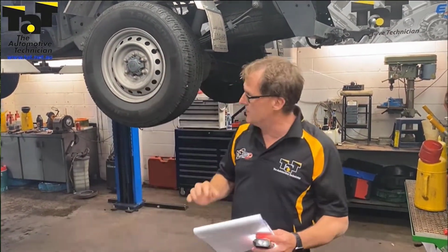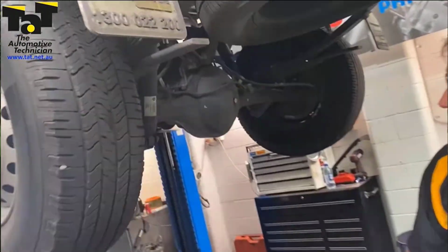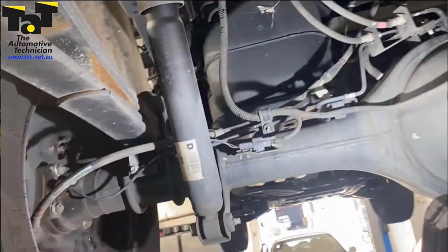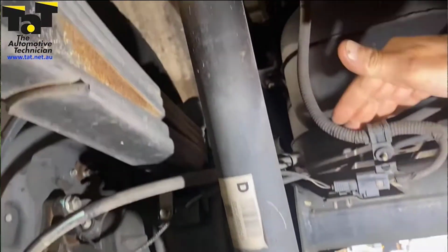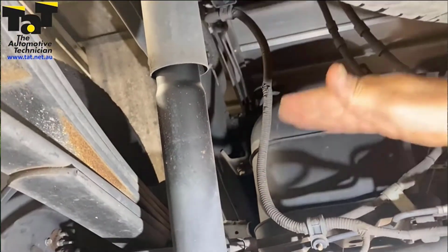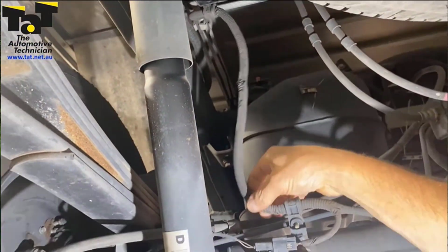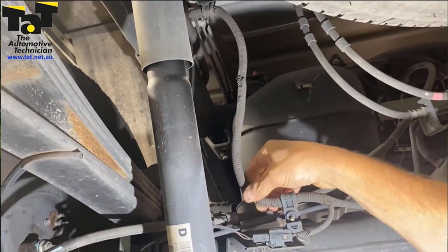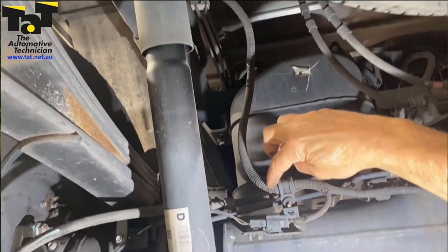So if it comes through, I can show you exactly what happens on this particular vehicle, and we do have a case study up on file for it. This harness here, we've got it on the hoist, so it's dangling down, but you can imagine once it's up, it's moving all the time. So this harness is going like this all the time, especially if it does a bit of off-road stuff, and eventually it breaks this wiring in here.